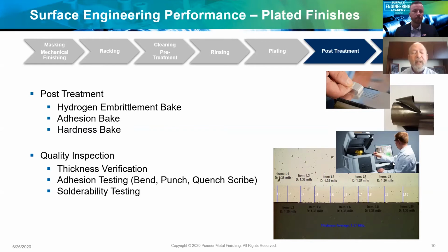There's also adhesion testing that's available to do either on the parts themselves or a referee sample, like a panel, whether that's bending the panel or doing impact punches on it to ensure the plating is holding up and doesn't pop off. And for the products that require solderability, there's testing for that too. Yeah, so Steve, really a myriad of tests, and obviously spec dependent. Specs will have all sorts of tests, whether there's stain tests or even chemical exposure tests. You could have a whole webinar on post-process testing or specs. Yep.